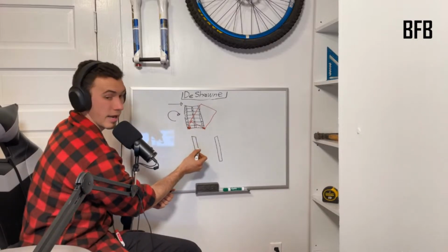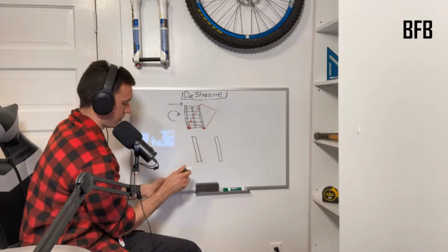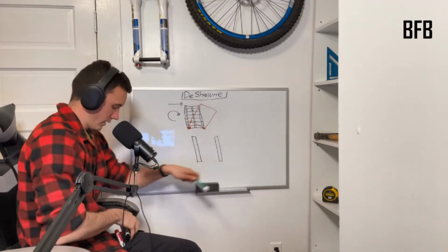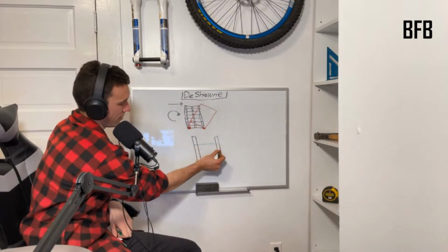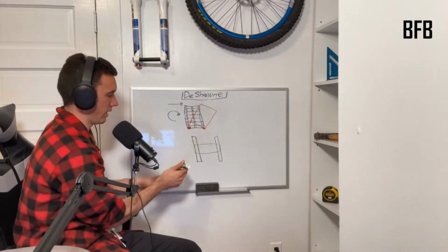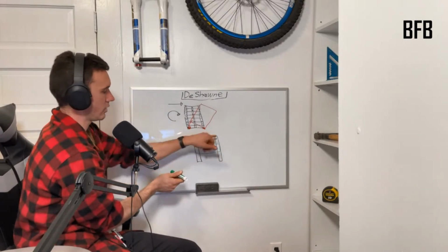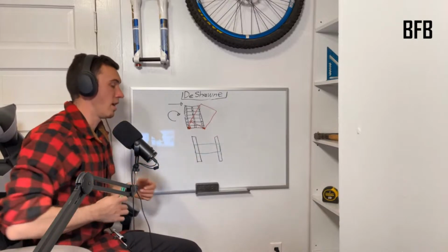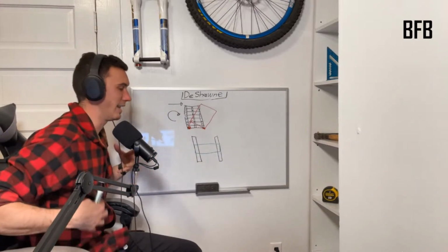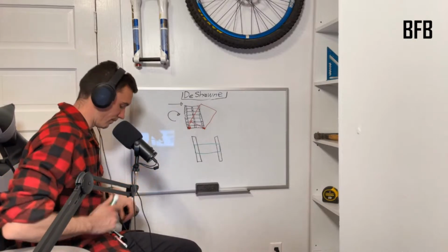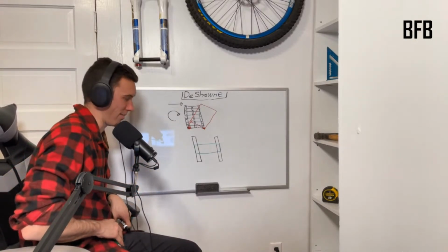Now, this is where the connections are important. If I take this plank, which is going to be green, because green is the color of planks, the plank goes on top of both boards like a deck plank. Think of this as you're doing your deck, right? So these are the deck joists. You put this deck plank on top. A deck is a diaphragm. Even though all these deck planks are disconnected, it acts as a diaphragm. Well, assuming you connect it properly, it does.